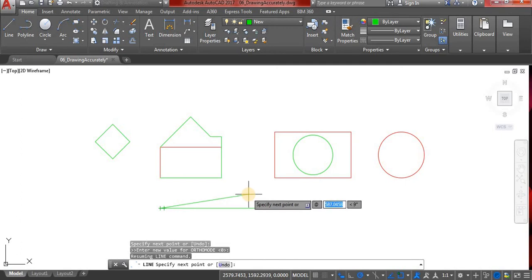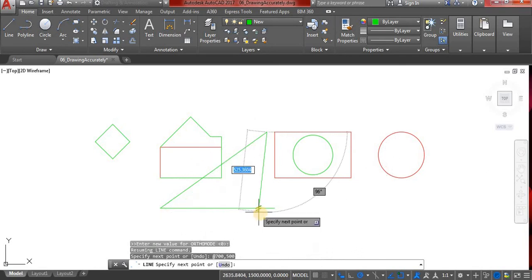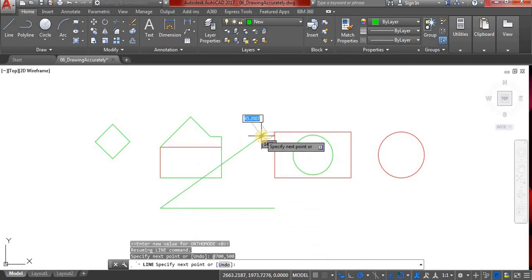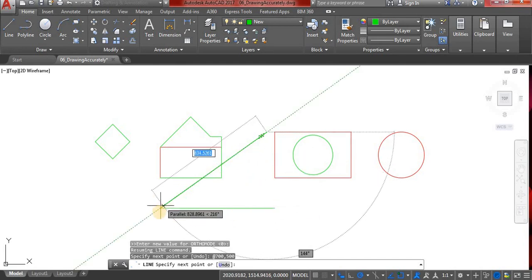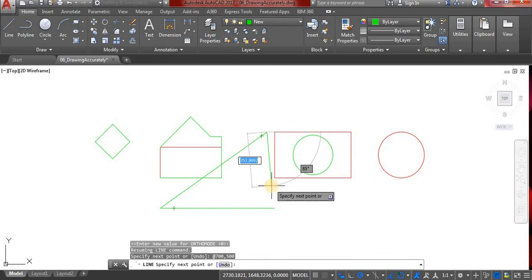Let's go ahead and I'm going to show you an example. So it's for example 700, and then a comma. It's next to M letter on your keyboard. The lock, it activated it, and the other coordinate, which is let's just say 500. Okay, so there it is. It's 700 in the X direction and 500 in the Y direction, in the relative to that point. And that's how we actually got rid of that angle sign.